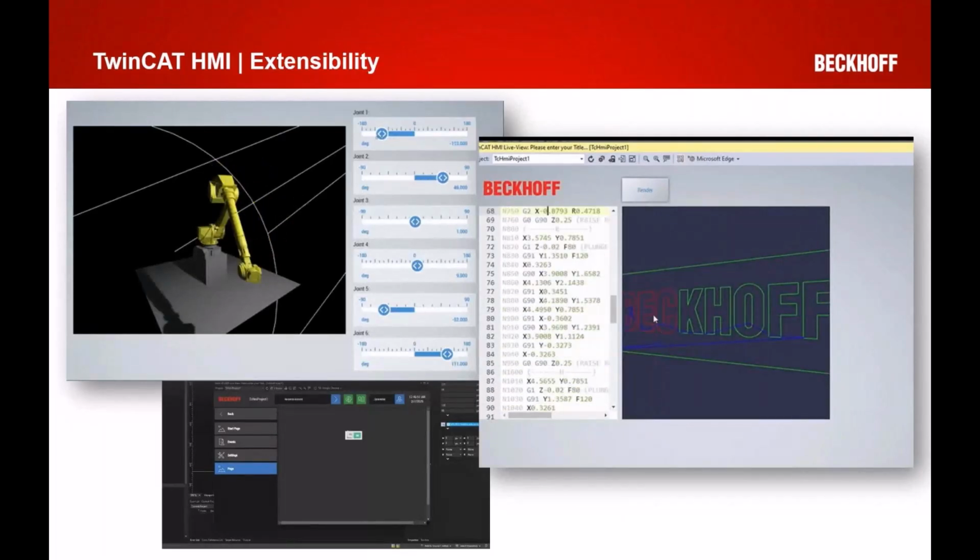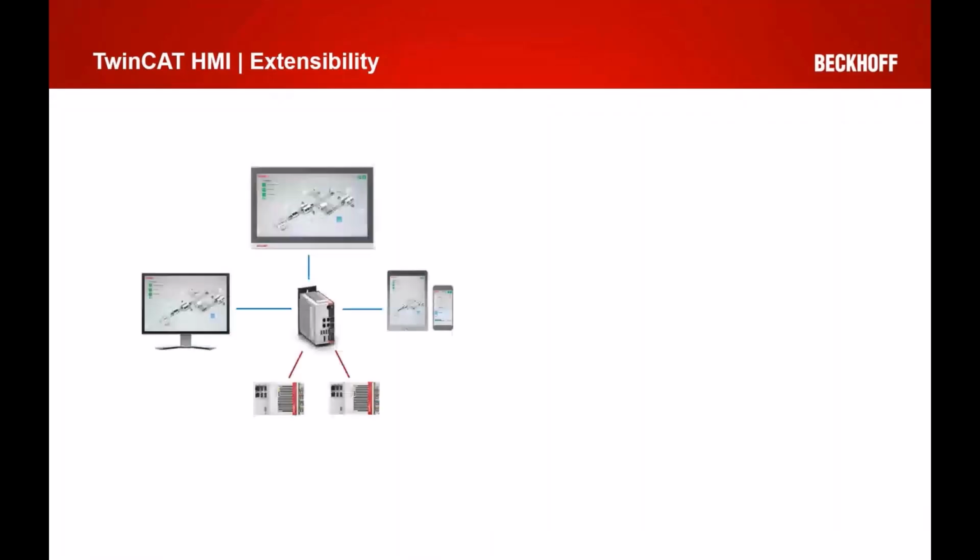Moving on to the back end, we run into a familiar modular approach. We only briefly talked about the server, how it serves the clients, how it handles the communication with the PLCs, but there's a lot of other functionality it accounts for as well. For instance, managing all the data for features like historization, recipe management, doing authentication or authorization for user management, connectors for the data behind some of our special controls like EtherCAT diagnostics or vision.